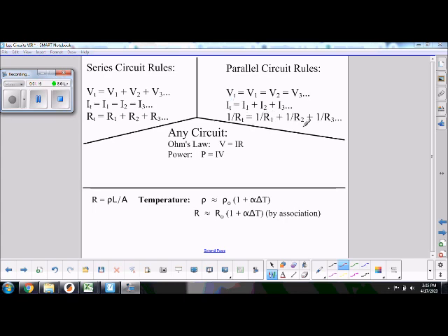And then you get the special equation for resistance of resistors in parallel. 1 over total resistance of that section equals the sum of 1 over the resistance in each pathway. And again, remember, you've compressed any series resistors in that pathway down to a single resistor. So each pathway would have 1 equivalent resistor in it. And don't forget, at the very end, if you've got an answer less than 1, you probably forgot to take the reciprocal at the end. In a series circuit, total resistance is always bigger than the biggest resistor. In a parallel section, the total resistance is smaller than the smallest resistor.